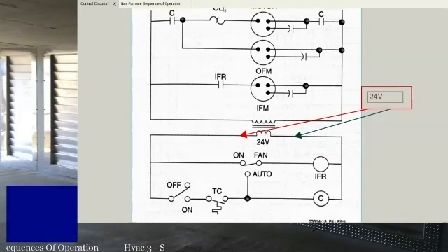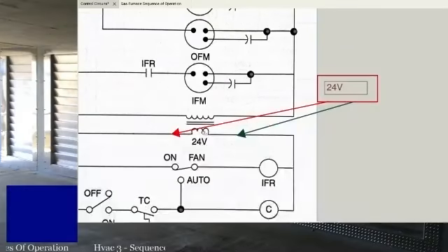Even though you should really start at the beginning, and if you've got a hard one you probably want to start at the beginning, if you start at the low voltage side of your transformer, or in a commercial unit with 120 volt controls, start at your main 120 volt transformer that feeds your main control boards, and everything is good at that point, then you've eliminated like 5 or 6 things right at the gate. That's always where I've started, right there at the transformer on the low voltage side, because that eliminates power coming in, fuses, everything.